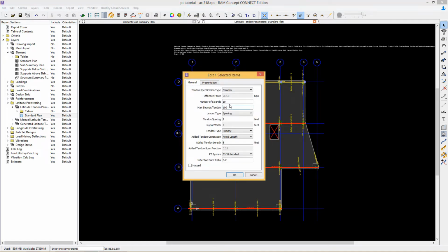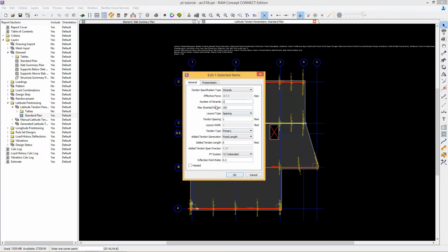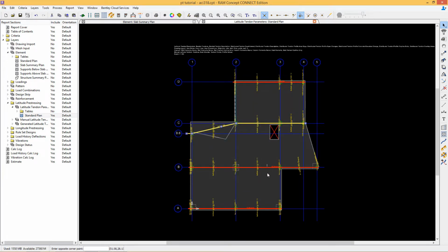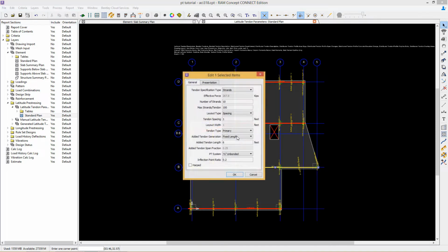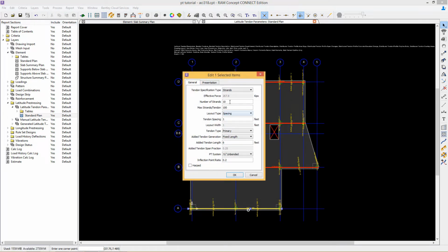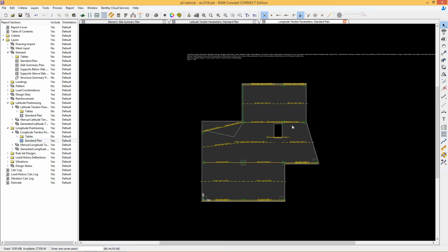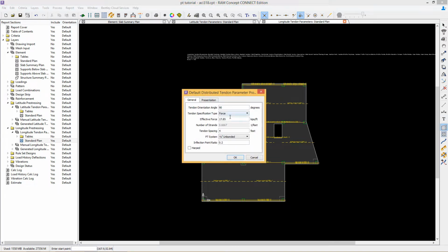So what I would typically do in the design process for this code is to set the number of strands in this direction initially to satisfy just the minimum level of pre-compression. And then we'll look and see at that point, after we do an analysis, if we have any failed code criteria, in which case we can add post-tensioning to try to resolve those particular criteria.